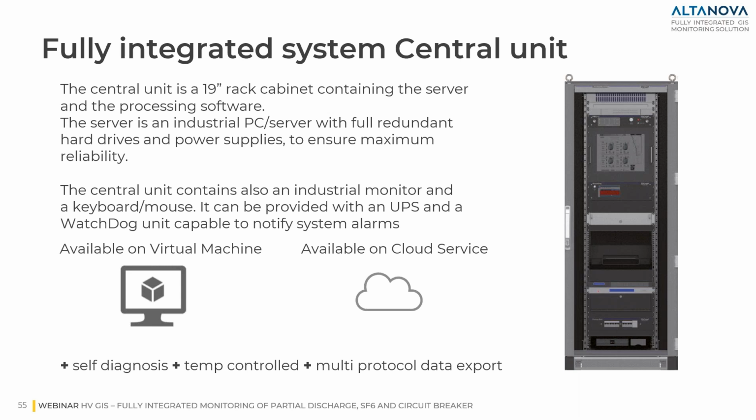This configuration is available not only on the physical server, but even in virtual machine environments that can be installed on existing hardware. And the same solution is available even as a cloud service. We integrate self-diagnosis in the system. Cabinets or even the rack are temperature controlled, and can be installed even outdoor. And we have the 61850 protocol, 104, OPC UA, DNP3, and many other protocols available on this system.